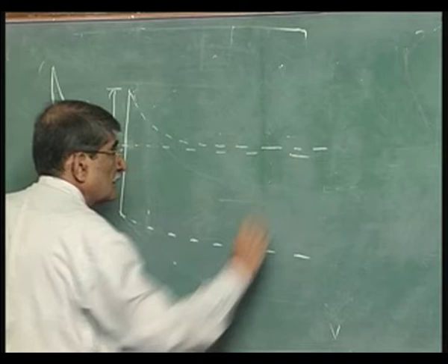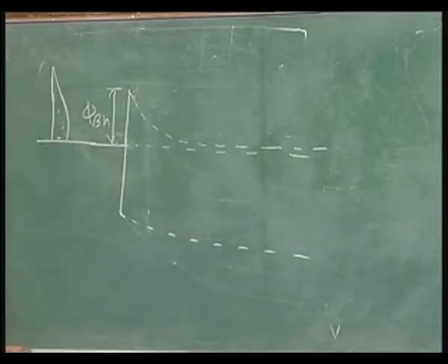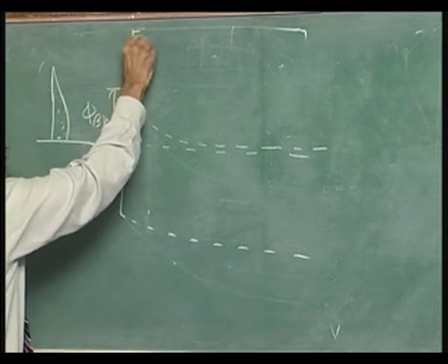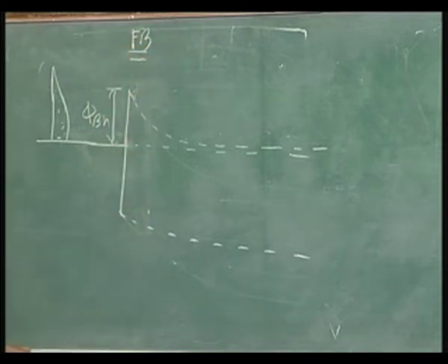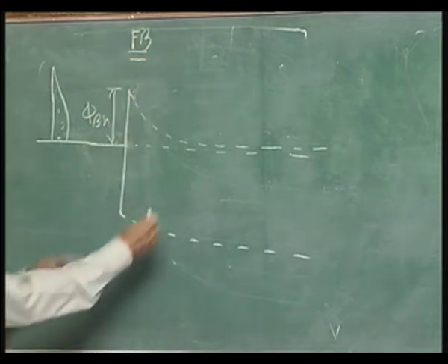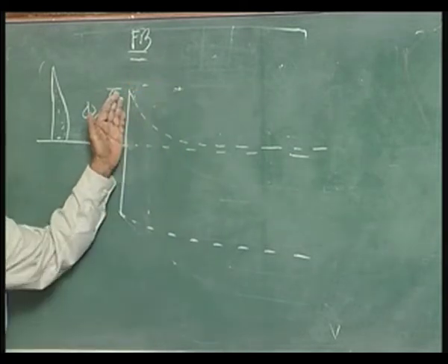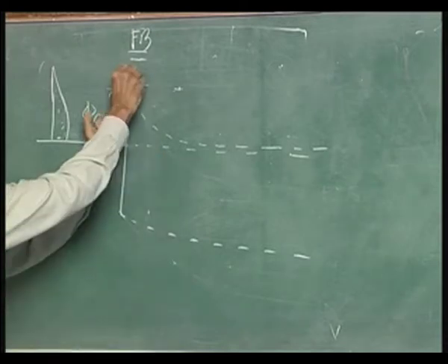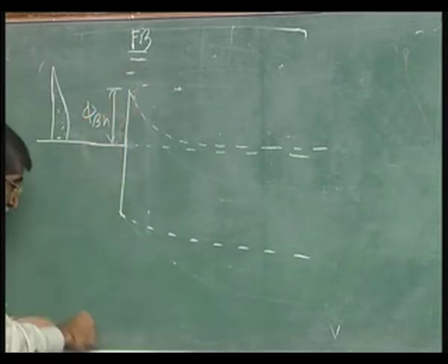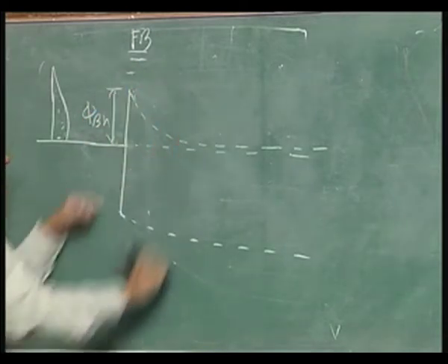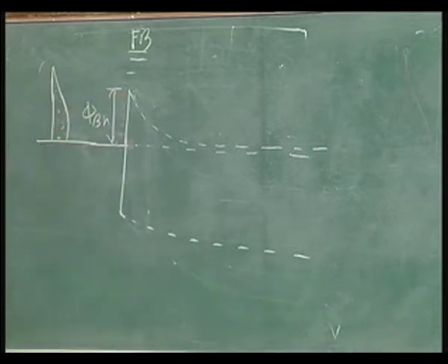Okay. That is thermal equilibrium. I am putting a dotted line because when you forward bias, FB, whatever barrier was there having a potential plus minus. If I apply plus minus there, like what you have done in the forward bias, you are reducing the potential across the device.